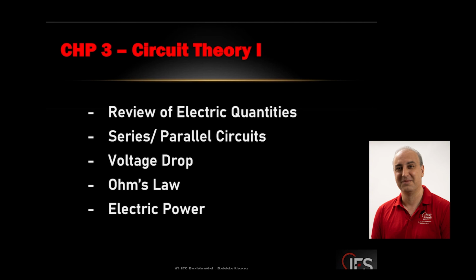Right. Well, typically, the resistance of a wire is small enough in short distances that we can ignore it. Now, it also depends. We're talking about our trade, right? We're residential electricians. We're looking at residential wiring. In some sensitive industrial equipment, even at 10 feet long, you have to worry about voltage drop, voltage regulators. Some systems are very sensitive. But for lights and devices and motors and things that we use in residential setup, usually with short distance the resistance is not big enough to worry about. Anything else?